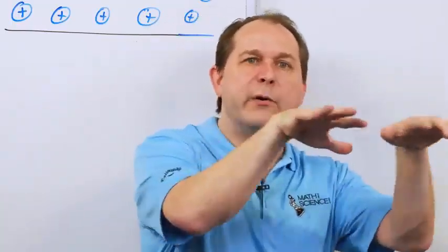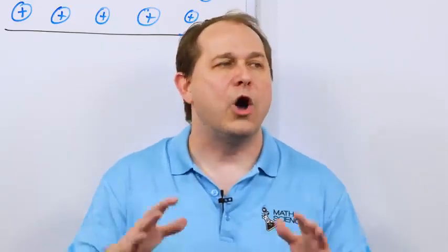Negative electrons flowing one way is the same as positive charges flowing the other way. Mathematically, they're equivalent. And we love to have positives in our equations instead of negative signs. Also, when we get into magnetic fields, the right-hand rule of the magnetic field is based on positive charges also. So it's easier to talk about positive charge flow almost all the time in electric circuits.